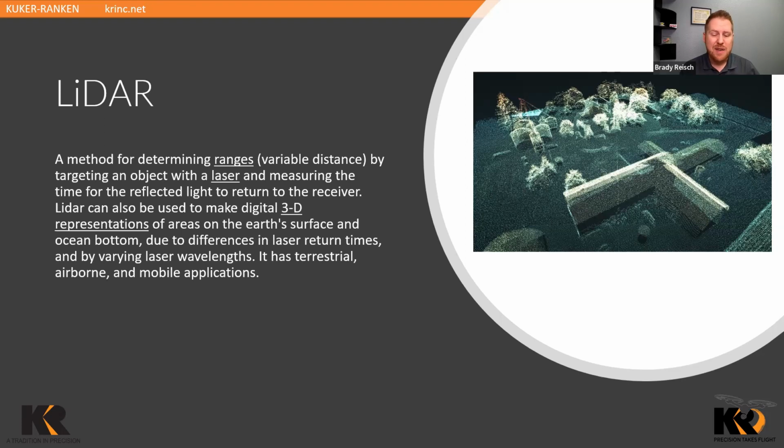There are different aspects of that, but that's something we'll get into later on with some of our other lunch and learns. Really the basis is that the laser getting shot out knows a specific distance that was captured from the sensor, to which we have a giant, almost like Excel, comma separated value file. It has an XYZ value, and it just generates that point cloud automatically or very, very rapidly compared to photogrammetry.